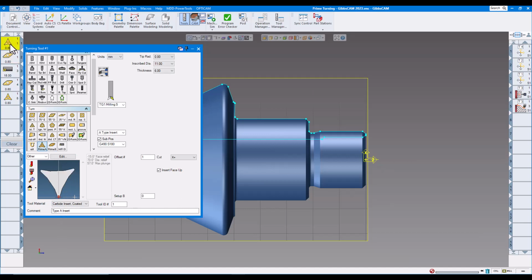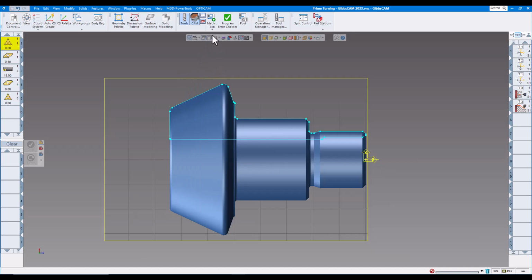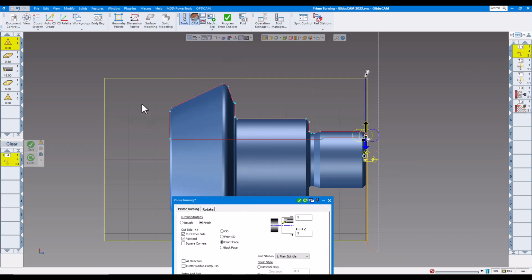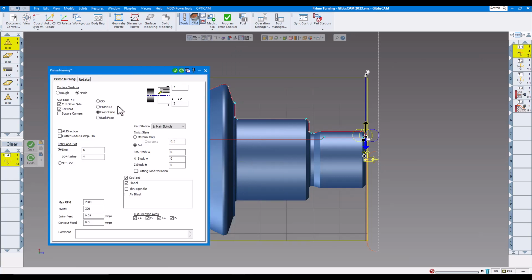And then we have this one. This is mainly for finishing, and this is more of a triangle shaped. So if we run the tool path, the unique tool path that we do is, of course, you want to pull with the insert. And as you can see, I'm starting below the part here and of course ramping on and cutting up instead of normally where we push the tool to go down for facing.